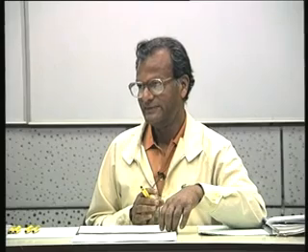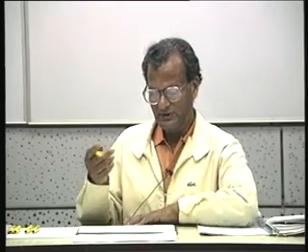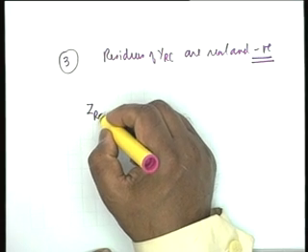All right. The next property that we derive, which is also useful, you remember that in the case of LC, the poles and zeros alternate, okay. And the first critical frequency is the origin. Origin is either a pole or a zero. The last critical frequency is infinity, which is either a pole or a zero. You will see that both of them differ in the case of RC. To derive that, let us look at ZRC of sigma.